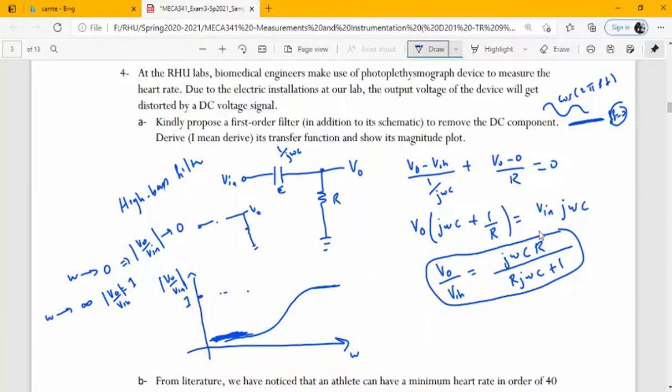Of course, we need to determine the cutoff frequency in practice. This is the cutoff frequency at which the magnitude is 1 over radical 2, about 0.7. If we need to modify this into a Bode plot, remember that this would become a logarithmic graph, and 1 over radical 2 is approximately minus 3 decibels.